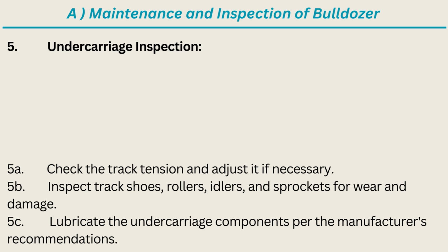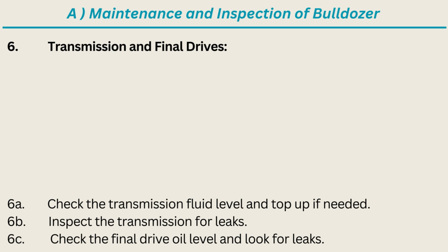5C. Lubricate the undercarriage components per the manufacturer's recommendations. 6. Transmission and final drives. 6A. Check the transmission fluid level and top up if needed. 6B. Inspect the transmission for leaks. 6C. Check the final drive oil level and look for leaks.